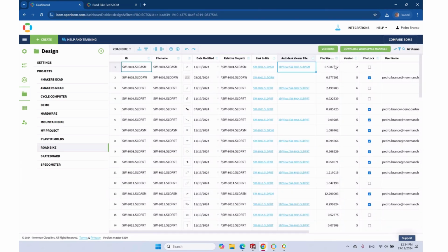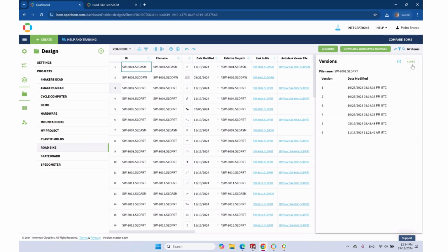So we also managed to solve the problem of multiple users working on the same file with the file lock mechanism. File lock, you can see that's check in, check out. We simplify just naming it file lock. It's just locking the ownership of the file, so you are locking the right access to you. So only you can upload changes. So this works through every time you smart sync. It also creates file versions automatically from files.